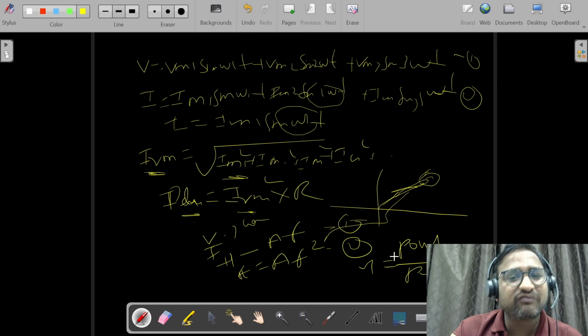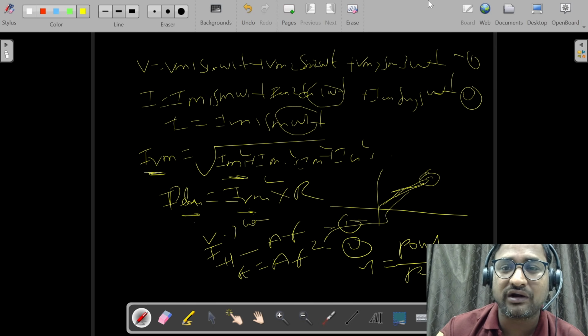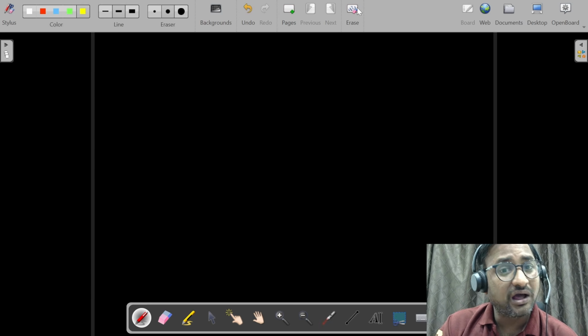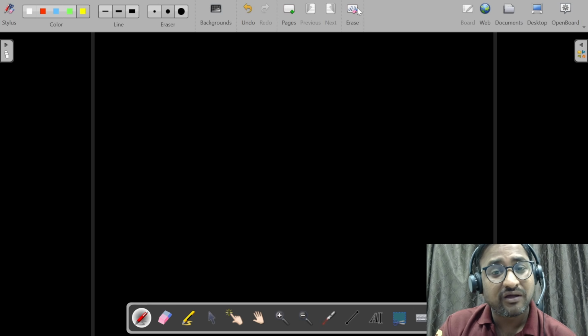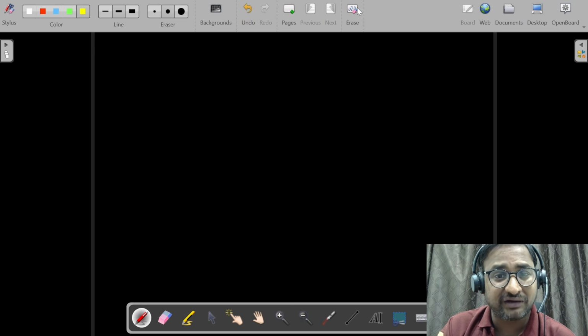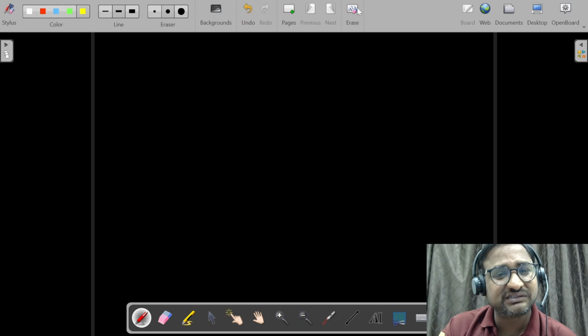Finally, what I've explained is, what are harmonics? Harmonics are nothing but unwanted frequencies present in the system. How are they created in the system? They are created when we use a switching element. The day when we use power electronic devices like IGBT, MOSFET, transistors as switching elements, harmonics come into the system.